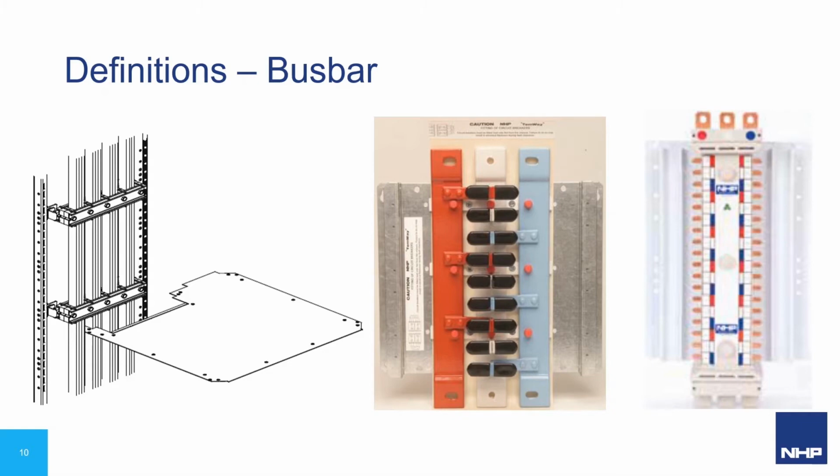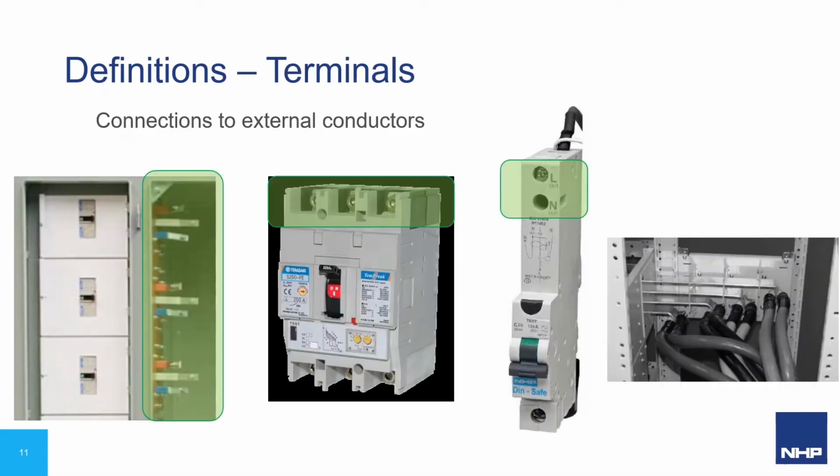In general, any conductor from the load side of our incoming unit to the line side takeoffs of our load distributing devices would be considered part of the busbar when considering a form of separation and its construction.